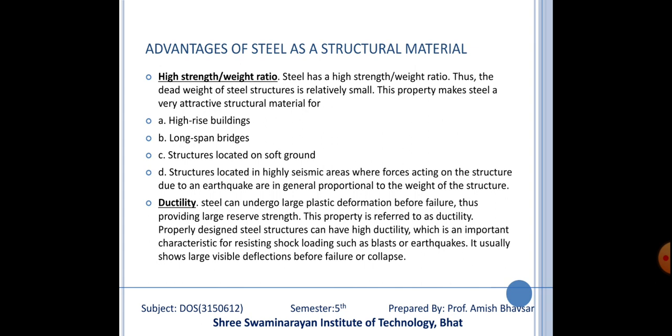First of all, what is ductility? Steel can undergo large plastic deformation before failure, thus providing large reserve strength. This property is referred to as ductility. Suppose earthquake force is acting, then the building deflects horizontally.